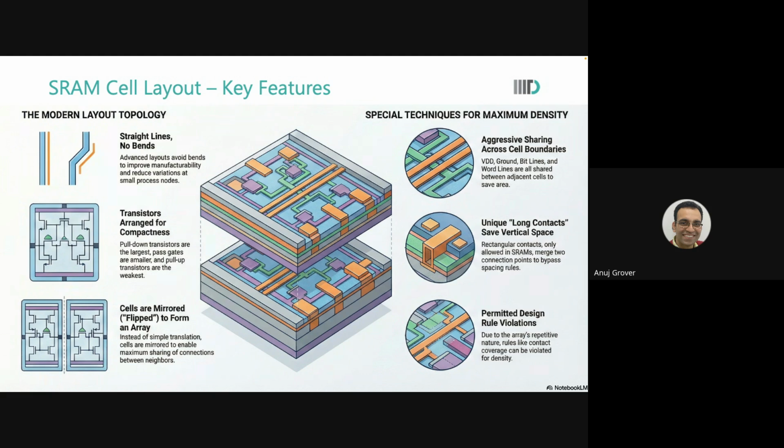We also arrived at the conclusion that in advanced technologies, in FinFETs, for example, the cell ratio is maintained as 1 only. It's not possible to do anything else. You can't have a fractional cell ratio in FinFETs, but it's kept to be 1. The only thing you can do about FinFETs is that, okay, change the length a little so that the pass gate is a little more resistive than the pull down. But in terms of width, it is the same.